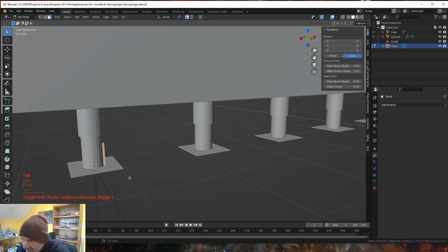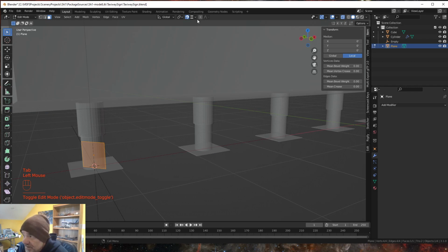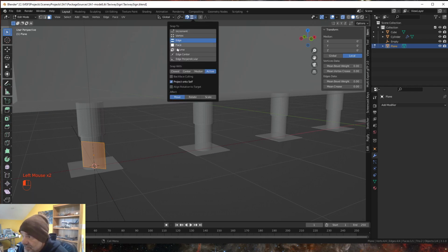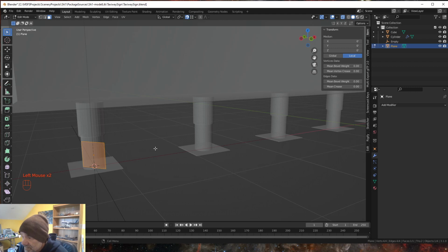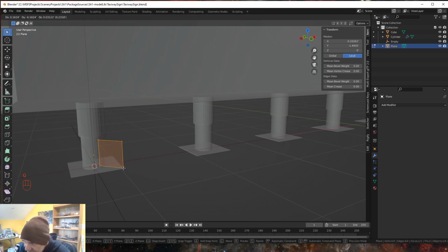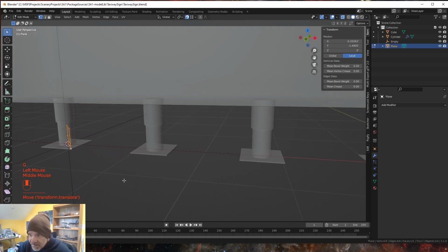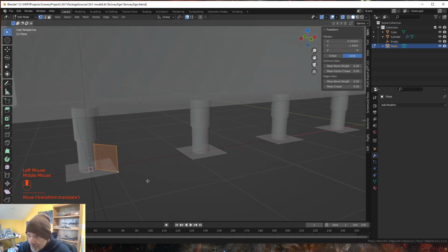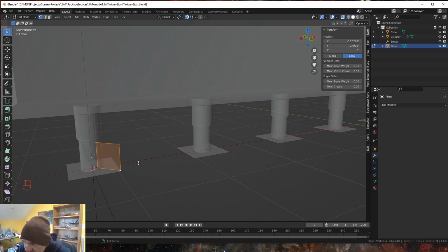I'm going to go into edit mode, go into ghost, and turn my snapping to vertex. Okay, and then make my edit feature vertex, and I'm going to Shift X, click, and make this vertex active, and I'm going to G and snap it right over here. Just like that. Alright. Now, they're kind of a triangle.